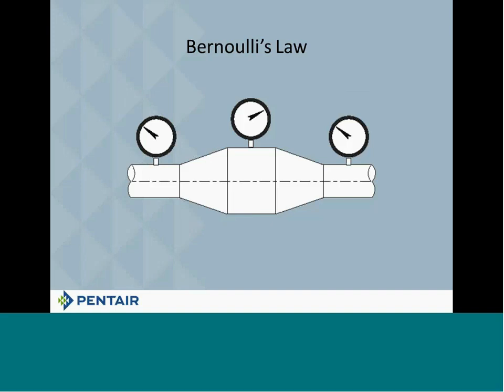Real life numbers, okay? The first pressure gauge is 8 psi. Remember, the second pressure gauge is going to read up, and so now we're at 16 psi. In real life, because of friction loss, that third pressure gauge is going to read less than what the first one did. All right? According to Bernoulli, it's all the same because he's measuring velocity head. He's not measuring friction loss. We're measuring friction loss. So that's why those pressures are a little different. But as long as we know that friction loss, it's energy we can add right back in. And that's the point. Okay?